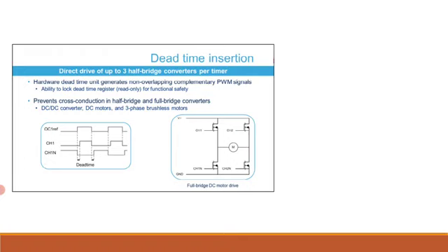In this case, it is necessary to insert some time before the switch on of one side to allow the other side to switch off, taking into account physical switching characteristics. Half bridges are usually found in DC to DC converters, for DC or stepper motor drivers using the full bridge topology shown here, or for 3-phase inverters with 3 PWM pairs.